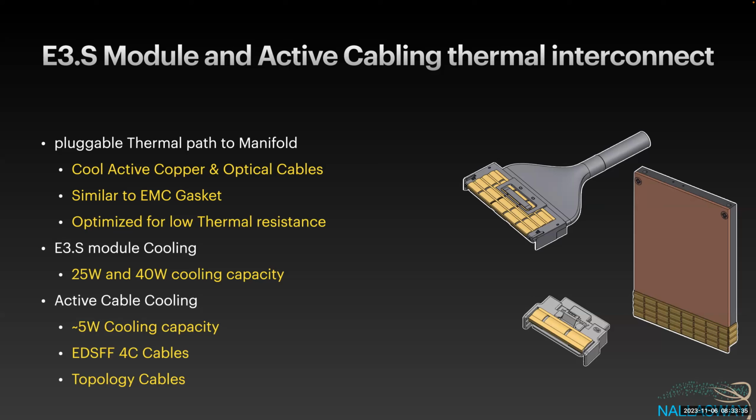And we would attach, for the active cables, instead of these huge QSFP modules, and we're going to OSFP as these things get even faster and more power hungry, with the promise of silicon photonics bringing those energy levels down and low energy chiplet retimers, I'm hoping and thinking that we can be in a 5 watt, and 5 watts would be horrendous to cool in such a tiny connector.